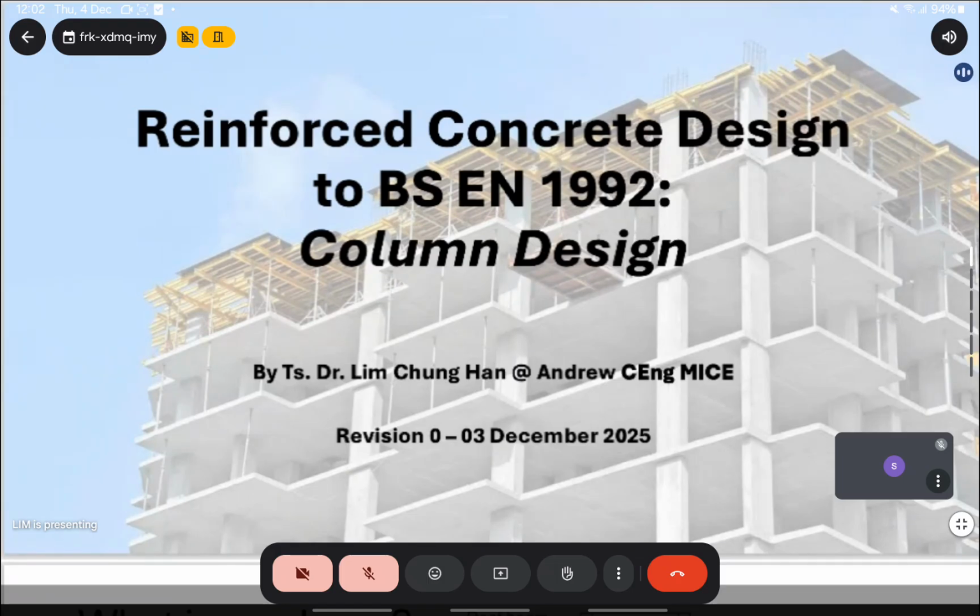It's inherently different from what we've done previously, flexural, shear, because it's not really governed by flexure, and it's not really governed by shear. Column design is governed by a mix of axial load and flexure, working together. So there's a bit of balancing act to be done there. You will notice that as I go through the presentation today.